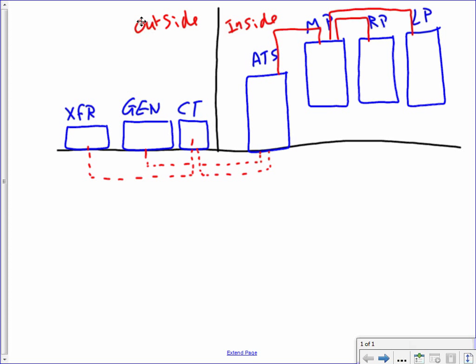So one more time, I want you guys to understand what a riser is. A riser is the backbone of the power system. It shows you the big picture. How is the power system put together? So we will put a transformer outside in the back of the building, and a generator. Why a generator? Because we decided to have a generator. Then a CT cabinet.